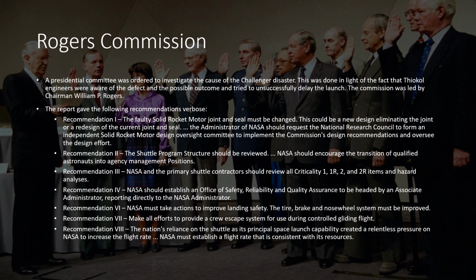The Rogers Commission's recommendations could be seen to reflect the event that took place the night before the Challenger launch. Thiokol engineers were aware of the O-ring deficiency and were aware that the O-rings would cause leakage in the system if temperatures were significantly low. During the launch day on January 28, 1986, temperatures were below -1 degree Celsius, which was far from the safe 12 degrees Celsius designed for the O-rings.